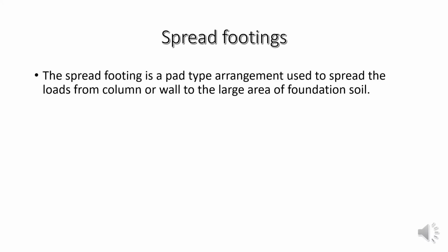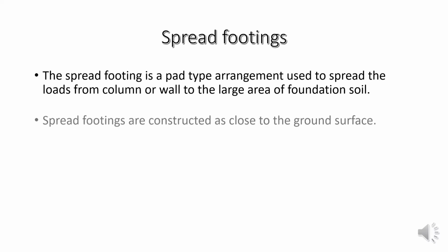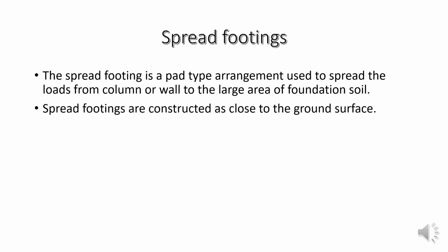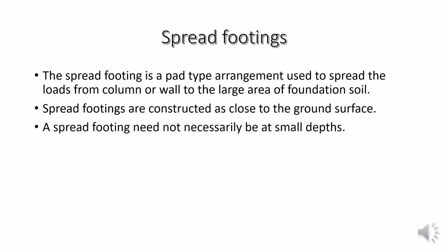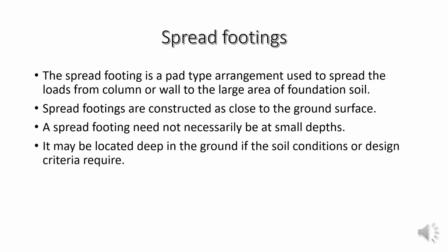Spread footings. The spread footing is a pad type arrangement used to spread the loads from column or wall to the large area of foundation soil. Spread footings are constructed as close to the ground surface. Yes, spread footings need not necessarily be at small depths. It may be located deep in the ground if the soil conditions or the design criteria require.